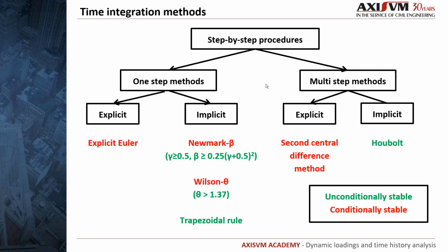implicit method. In case of explicit methods, the calculated responses in a time step only depend on the response values obtained in preceding steps. There are no coupling conditions between the new response values. An implicit method is much more complicated. New responses are obtained by solving a system of coupled equations, and the equations contain also responses calculated in the same current time step. The color code indicates if the method is unconditionally or just conditionally stable.